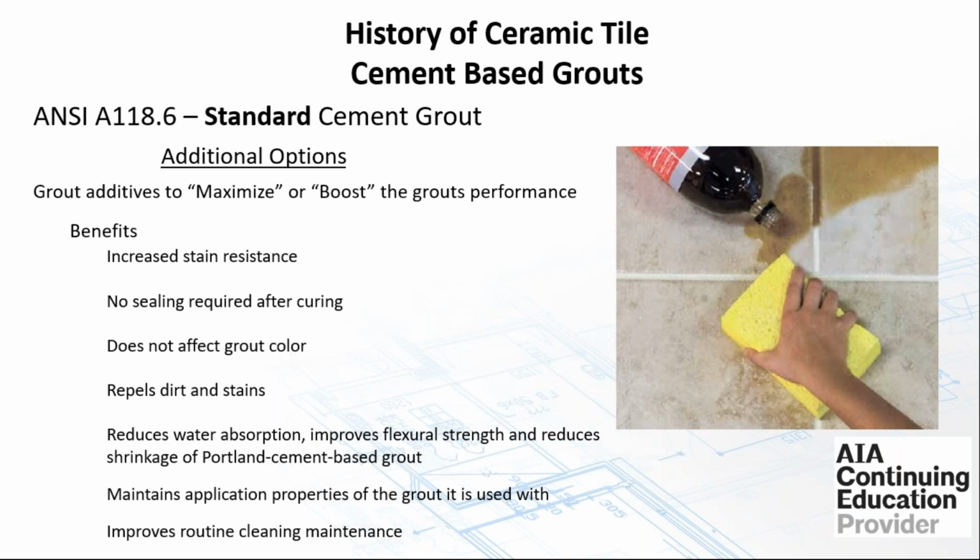Some of the other options we're seeing with these types of grouts is that we're starting to see maximizers or boosts, additives placed into the grout, even though they're polymer modified, again helping increase stain resistance, reducing the need for sealing, in some cases no sealing required after curing.